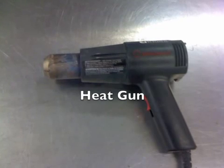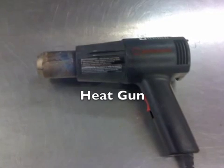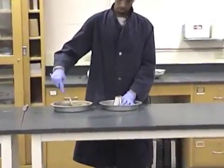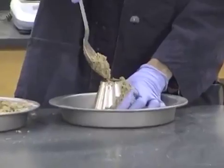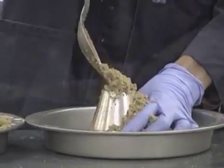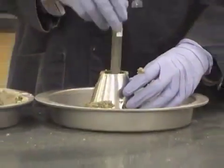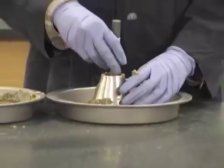We will also be using a heat gun to provide a warm stream of air and assist us in getting the sample to SSD. To perform the cone test, we want to hold the cone firmly on a flat, non-absorbent surface. We then want to add material into the cone, filling it to overflowing, heaping additional material over the top as necessary. We then want to tamp the material into the mold with 25 light drops of the tamper. The tamper should be approximately 5 millimeters above the fine aggregate for each drop.